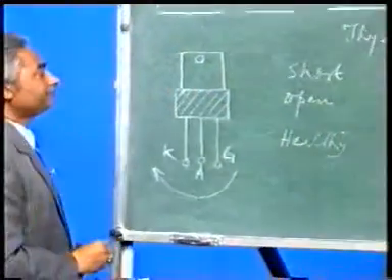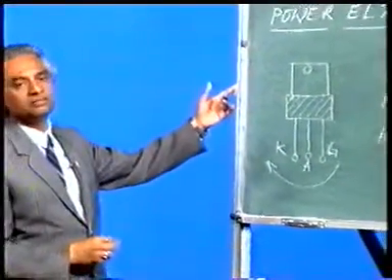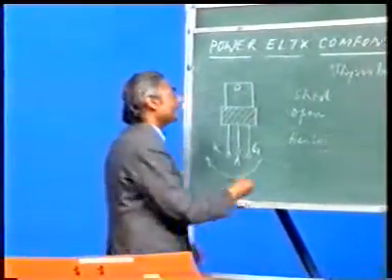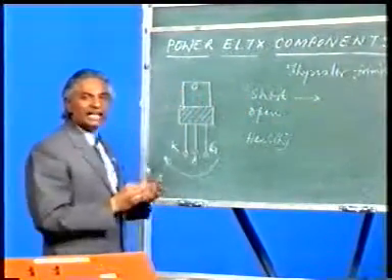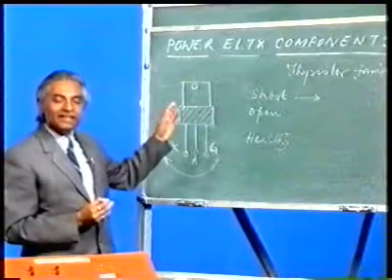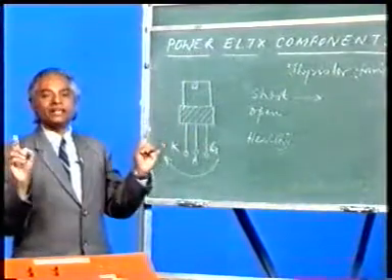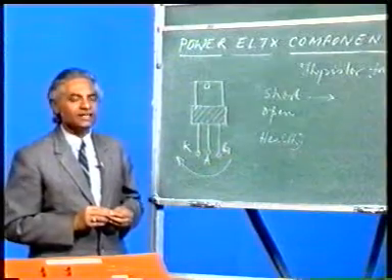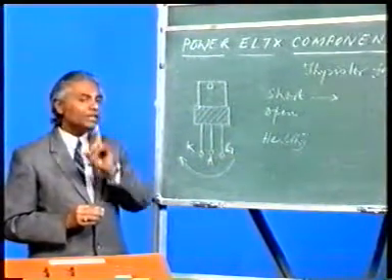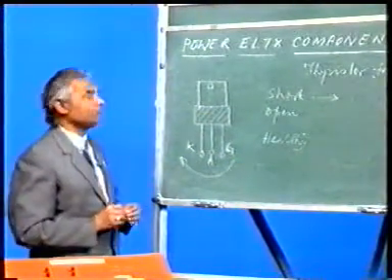or it can be healthy. If I find out the resistance between anode and cathode, the extreme terminals, you have seen that they have 3 layers, so it will give you very high resistance. But between G and K there is only one barrier, so resistance will be lesser.